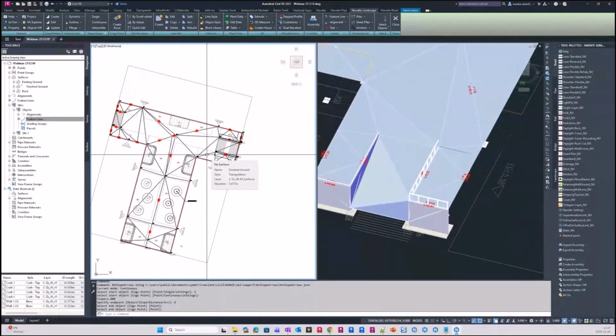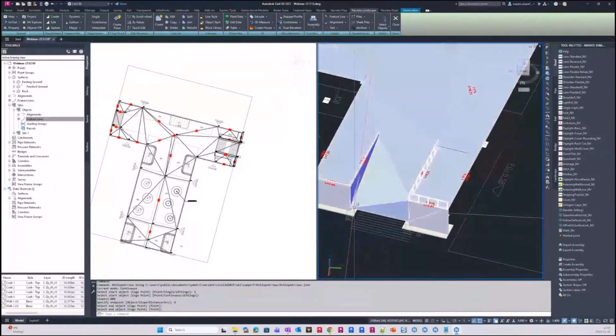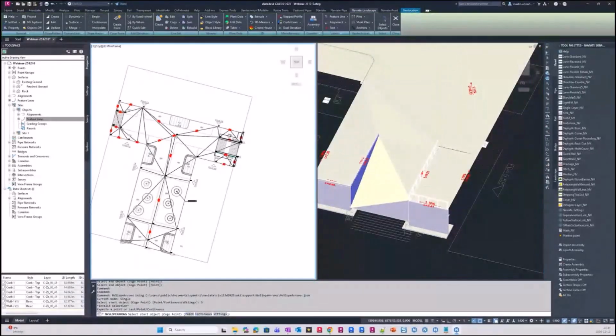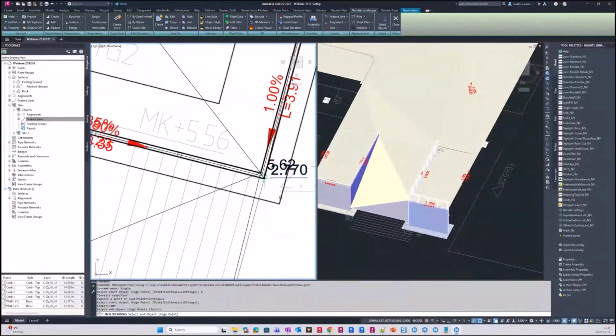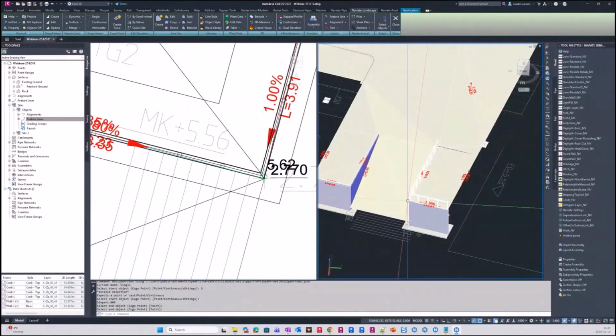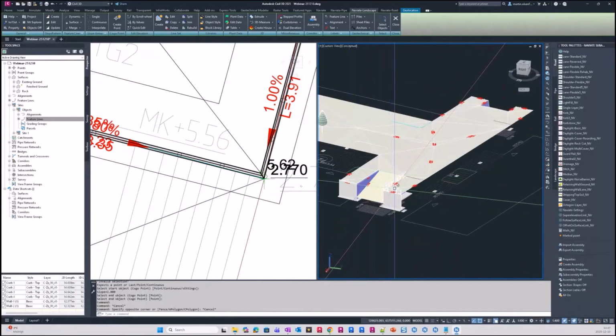Good. Thank you for this. We got a final question that I just answered, but I just want to mention it. We talk a lot about IFC exporting right now, and usually we talk about IFC export to 4.3. The solids that Martin showed, the supporting wall and the railings, those are solids, and the IFC export can export solids, but you need to add a property set so that it actually knows what it's supposed to export, because otherwise a solid will just be a random object. So that's the good thing about creating solids for this and not just having them as lines, because lines don't export with IFC.